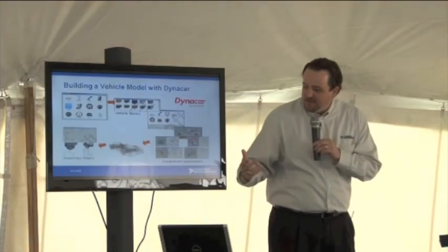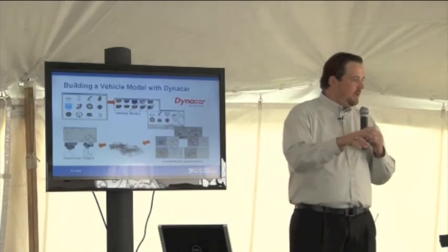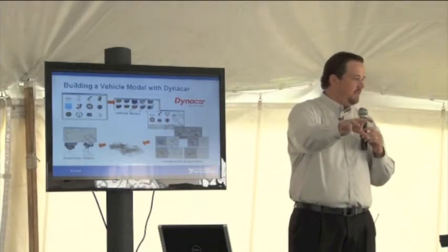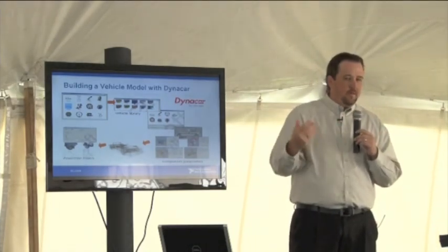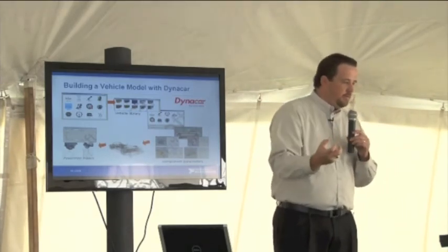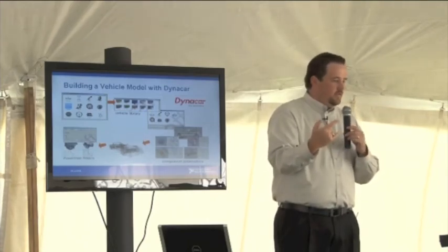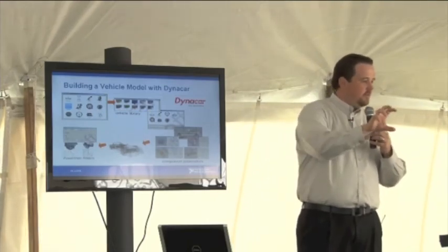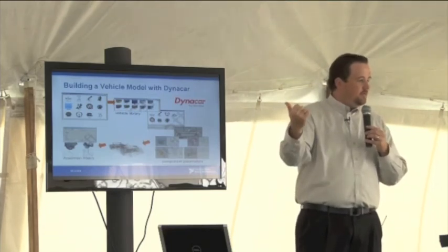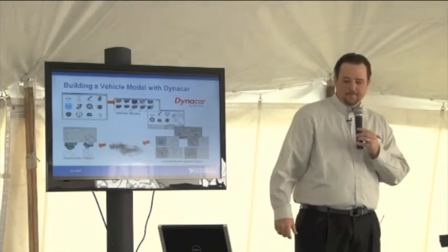And then you can simply pull out of that model any part of the system that you want to physically test. And we'll talk more about that here in a little bit, but essentially you have a complete vehicle simulation and you pluck out, let's say, the torque converter from that model, and then you take the inputs and outputs to that subsystem and map them to your dynamometer so that you can do the motoring and the loading of that physical component that you need to do there.